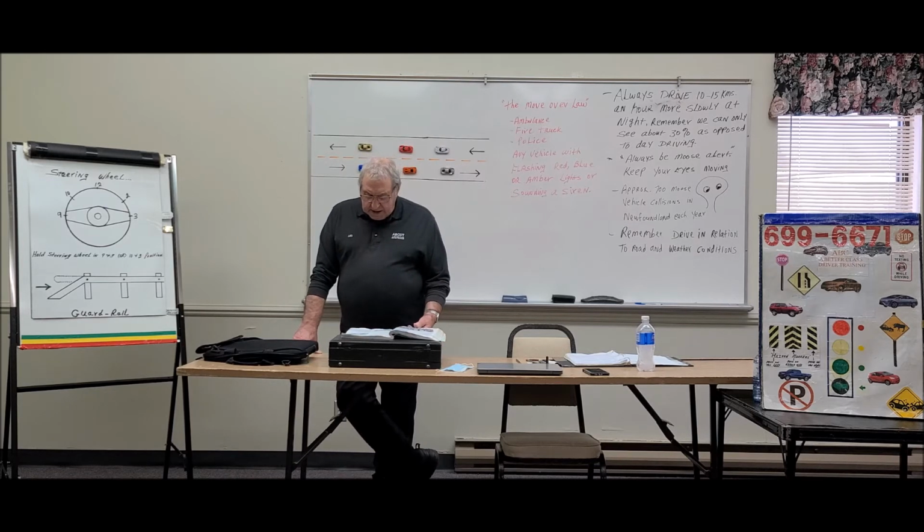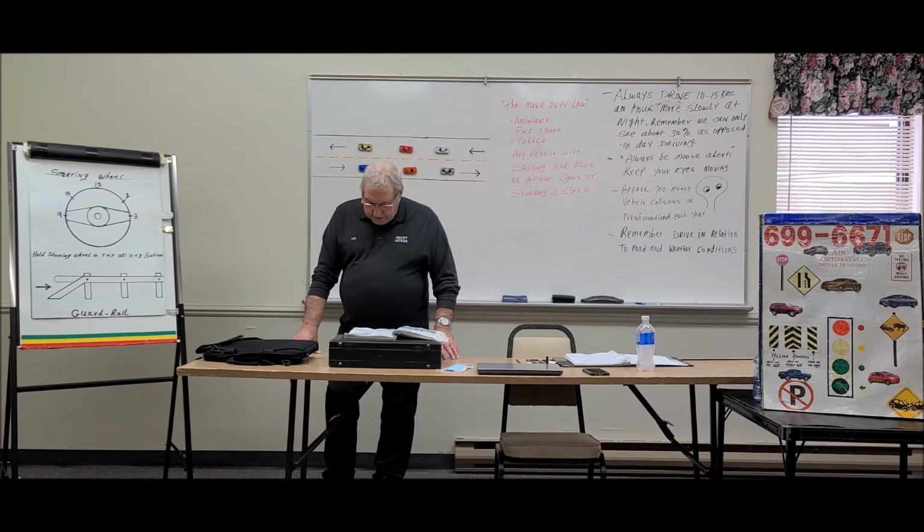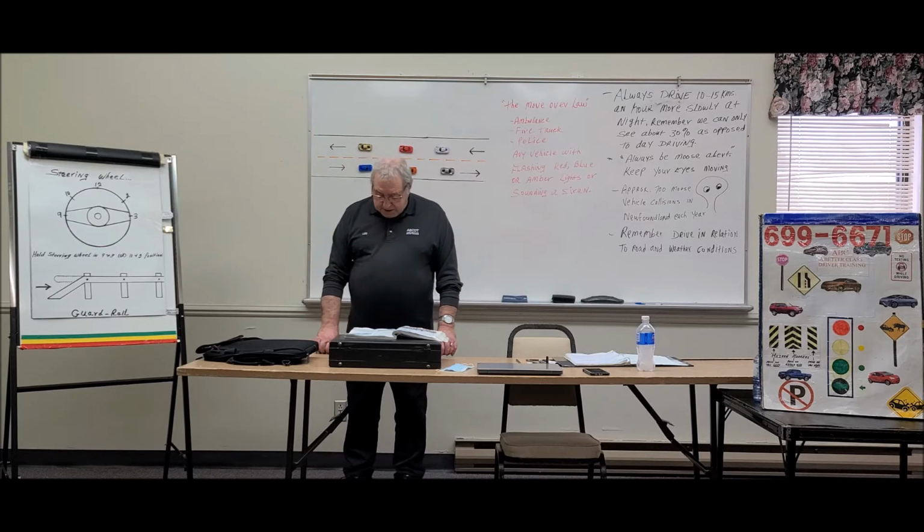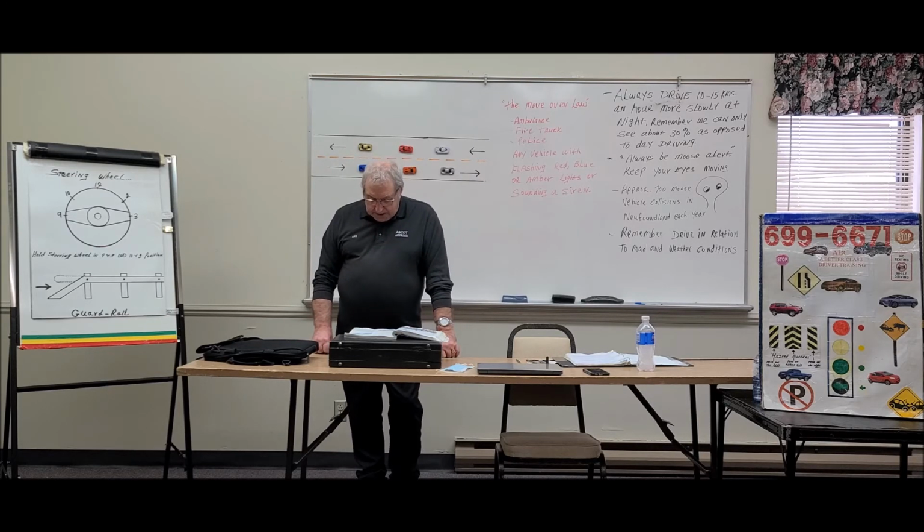So, again, the cockpit group, that's very important. The ignition switch there, let's say, locks the position. The steering wheel is locked. Most electrical systems are inoperative. The off position, most electrical systems are inoperative. The steering is not locked. The accessory position, accessory electrical systems are operative.